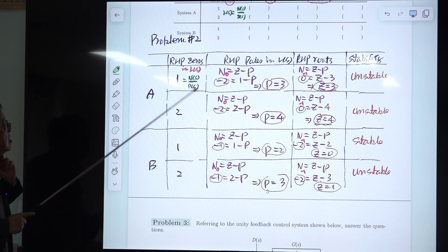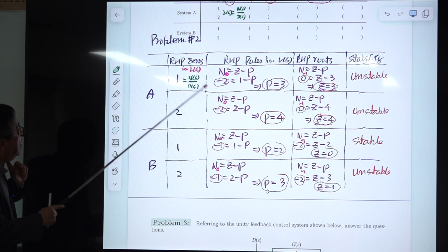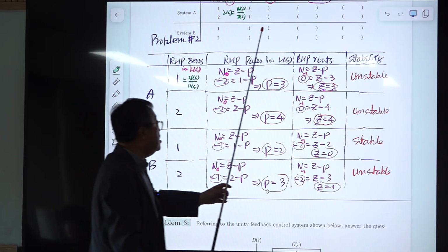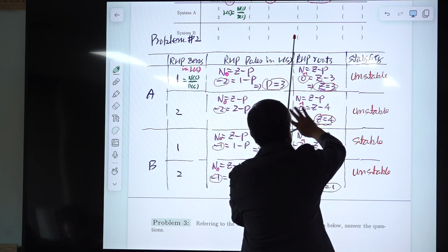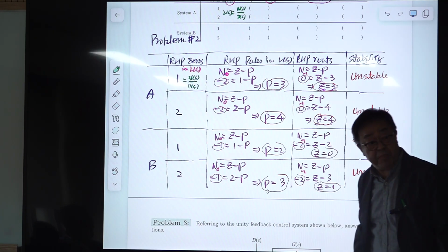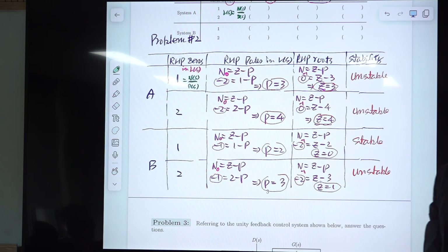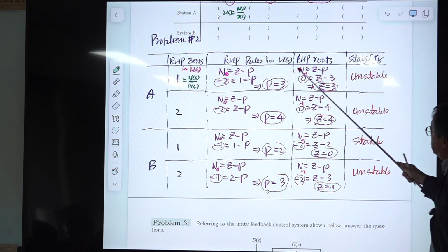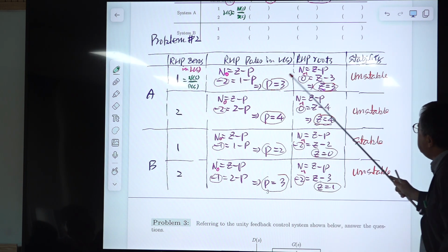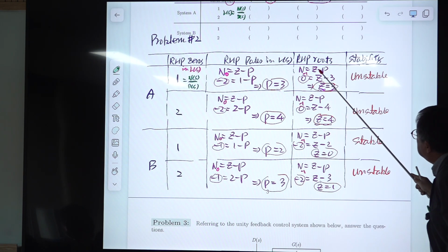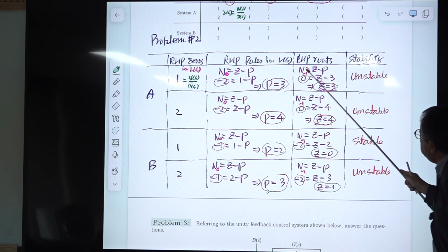Okay. So that means this denominator equal to 0 has 3 poles in RHP. This is the meaning of this. This has nothing to do with the stability theory, but it can be considered as an intermediate step or an application of Cauchy's theorem. And this is the Nyquist theorem. The RHP root count is given by this, but the encirclement point is not the origin, but this -1, 0. Okay? And this P is given, and N is known.